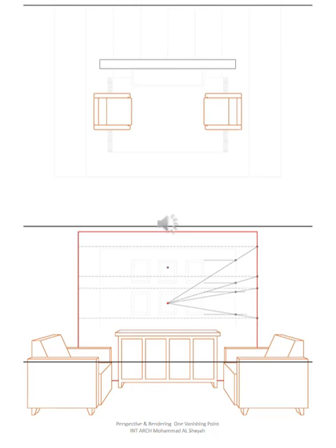Now starting with the photos hanged on the wall, we will start by projecting lines from the vanishing point to the corners of these photos, as shown in the figure, thus forming horizontal dashed lines where the photos should be located in the perspective. Now drawing the cadres of the photos using the vanishing point. Next, drawing the upper cadres of the photos also using the vanishing point.